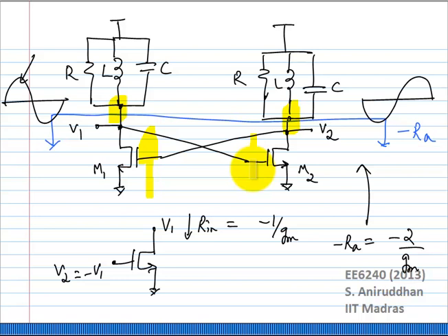Okay, in reality, most of these oscillators which you measure in the lab, that's what will happen. You turn on the power supply, and there will always be small mismatches between M1 and M2, and that jerk will be enough to not allow the circuit to settle down at its metastable point. In any real oscillator, that is what will happen.